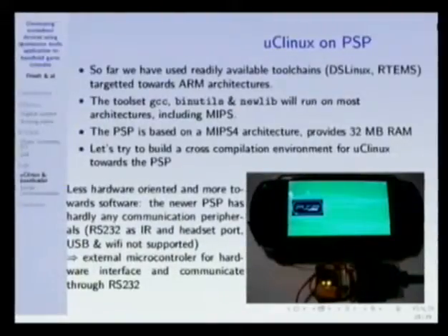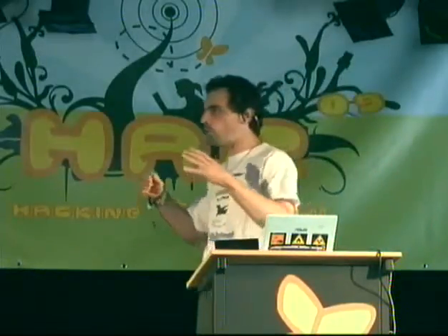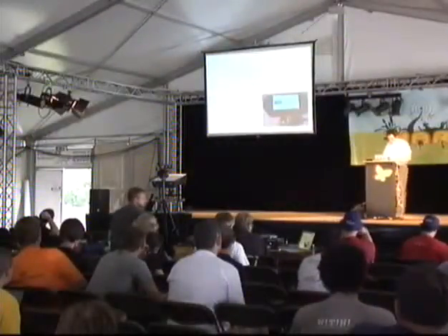for running uClinux. And our purpose about a year ago was to run uClinux on this system. Now, this was after someone from the US, whose name I'm unable to pronounce, Chris Mulder something, had done most of the work. And his problem was that he did not have a coherent tool chain for generating both the Linux kernel and its applications. He could compile the Linux kernel, boot the Linux kernel, and then it crashed. All his applications were incompatible with his Linux kernel.